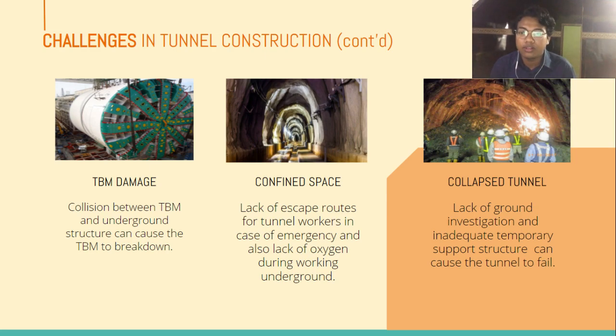Number 5, lack of escape routes for tunnel workers in case of emergency, and also a presence of gas and lack of oxygen during working underground in the confined space. And last, lack of investigation and adequate temporary support structure can cause the tunnel to fail, and the tunnel will collapse while the work is ongoing.